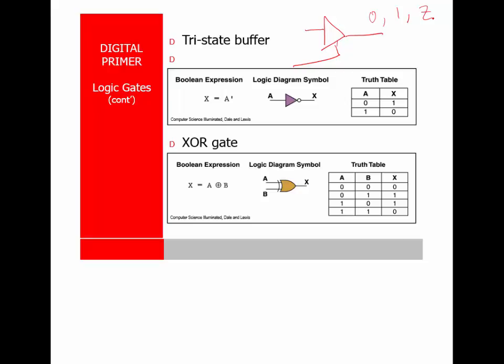This circuit here is a NOT gate, or an inverter. And the only difference between an inverter and a buffer is this little bubble right there. That little bubble at the end there. And you'll see that bubble when we look at the pinouts for the 8086, for example, and we will look a little bit at the 8086 in terms of the hardware discussion. You'll see the little bubble quite often on pins.